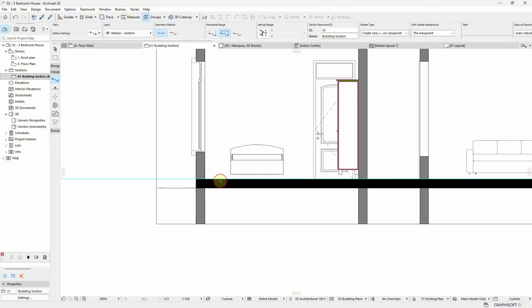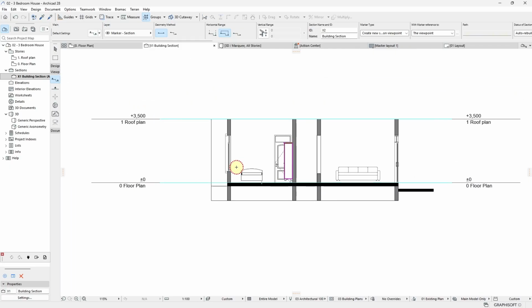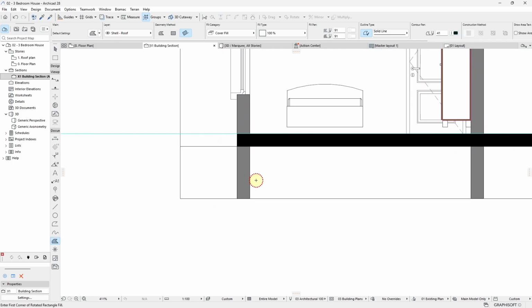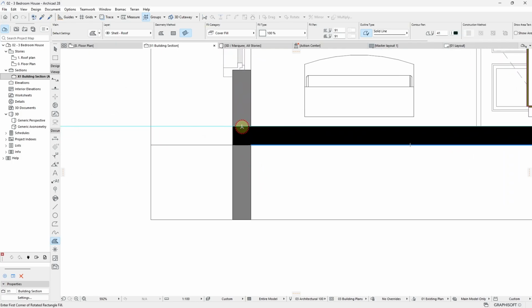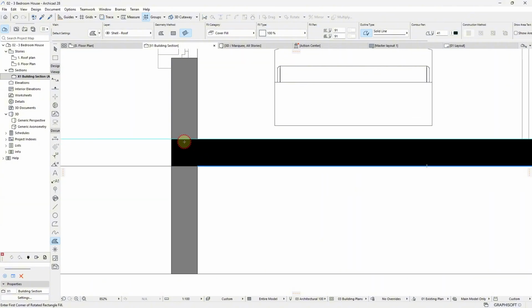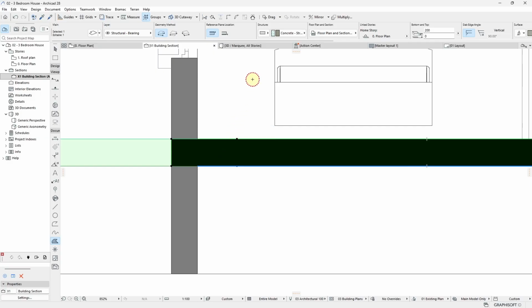So what happens is that when I'm doing my project, this is my zero level for the floor. I start from my zero level and I put my walls intentionally. Now, when I'm doing the height of the building, for example, here my floor to floor height is 3.5 meters. And then intentionally, I usually let my walls from the ground floor go deep down by 1 meter. This helps me to do my foundation, and it helps me to do other things below the ground. So I intentionally make sure that my building goes down by 1 meter, and then the floor slab starts from 0.